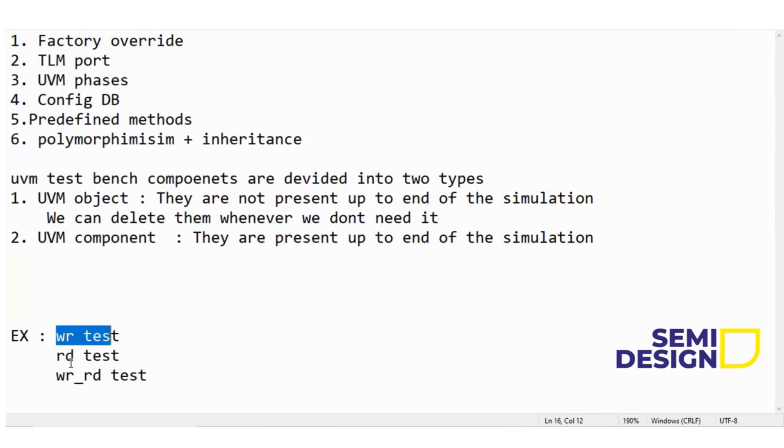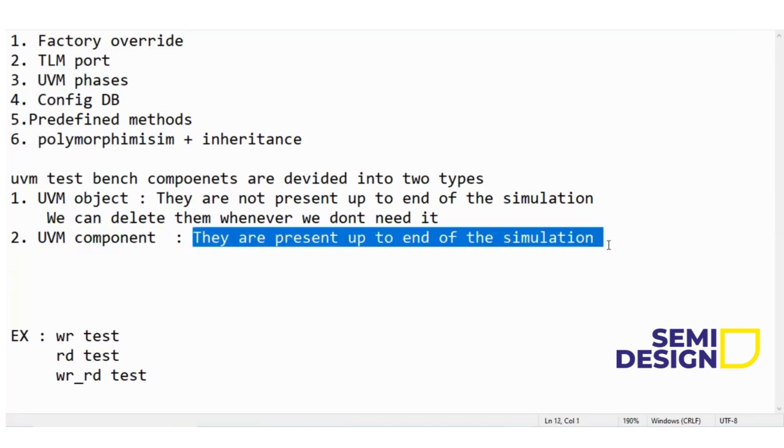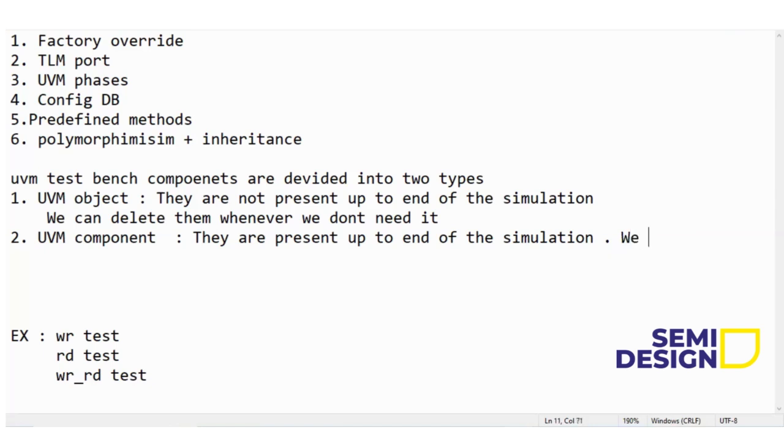The driver is the same. You cannot delete the driver, because from the start to the end of the simulation the driver should be there. Else, who is going to drive the values to the interface or to the design? So the driver is a UVM component because it is present up to the end of the simulation.